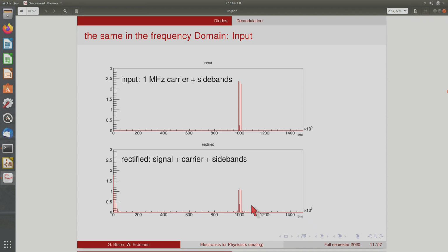Then if you rectify the whole thing, you also get these very slow components that are near DC. So you introduce these signals here, and this is what you really want to have. So now these frequencies are really just a nuisance. You want to get rid of them, and all you want are these frequencies, and that's why we added the smoothing and the low-pass filter.